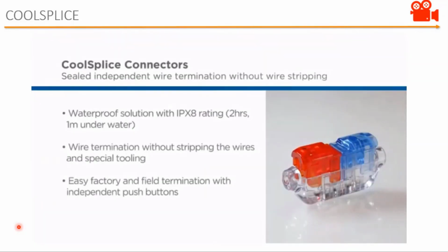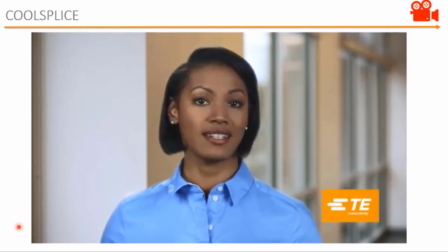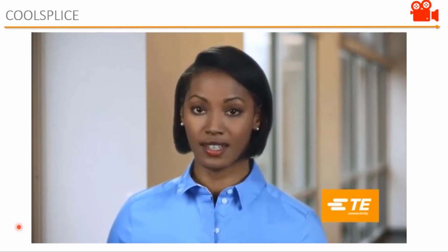Developed for splicing both solid and stranded wires, Cool Splice connectors are gel-filled and IP-rated to protect connections in wet, damp, and outdoor environments. The design permits quick push-button terminations that help to eliminate the need to pre-strip the wire and uses only a common pair of pliers while still providing an industry-proven reliable connection. And for ease of use, wires are terminated independently, allowing for the factory pre-termination of one wire and field termination of the second during installation.